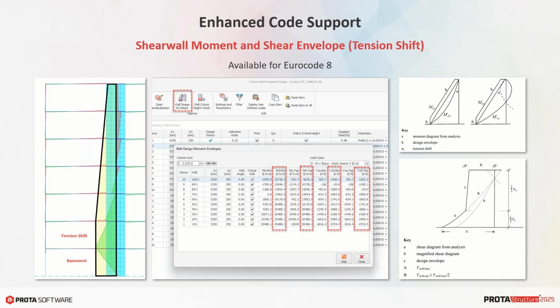Another important improvement in the new version is the use of tension shift in shear walls according to Eurocode 8. ProtaStructure will now automatically calculate the tension shift and apply the moment and shear force envelopes according to the procedure outlined in Eurocode 8.